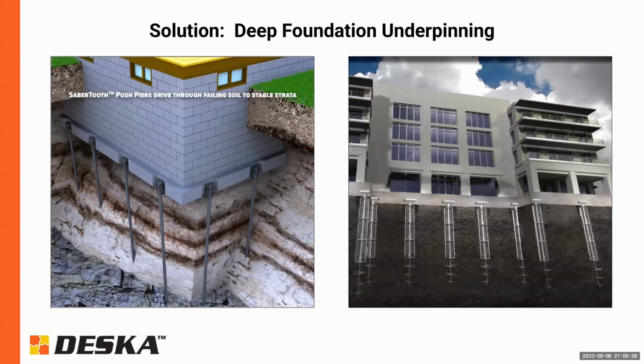So some other examples, for instance, like that house in Arlington with the serious undermining. Really, the only solution for that is what we call helical piers, and that's on the right side here. They're essentially like giant screws that get screwed into the ground, and the amount of torque that they're screwed into the ground with is directly proportionate to the capacity of them.